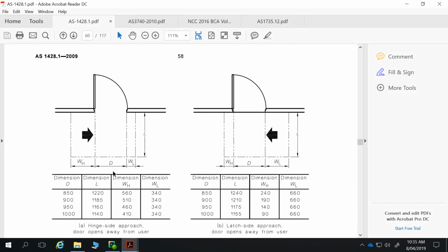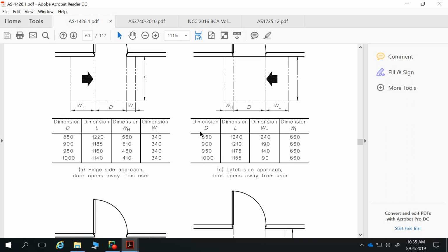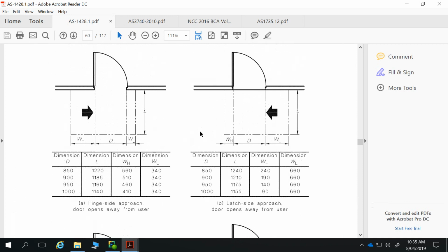But the important one is on this page 58, and this is where it requires a little bit of lateral thinking in regards to how we're looking at the doors. With that project, we have the balcony at the front, that's that movement space, or the approach for each of our units. Now, each of our units has to enable disabled access. To that, the doors have to comply with that.